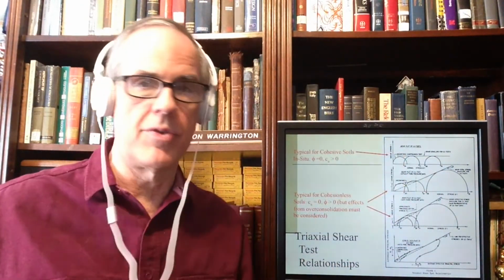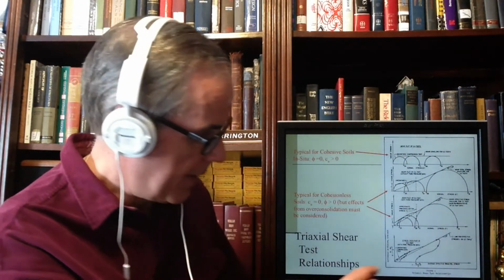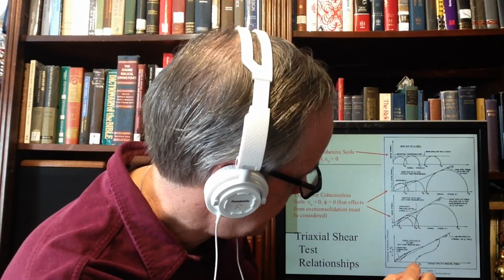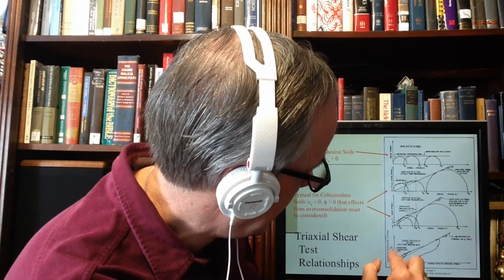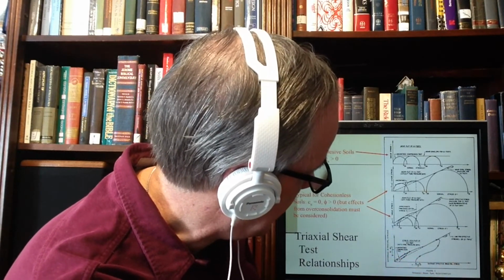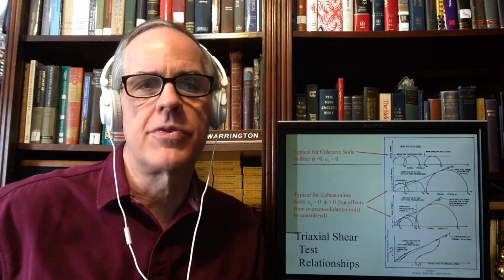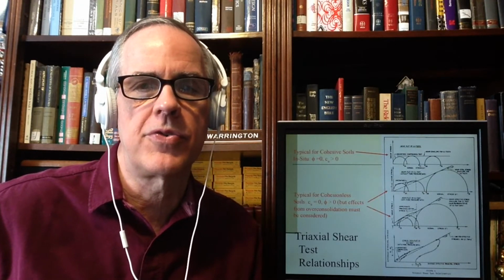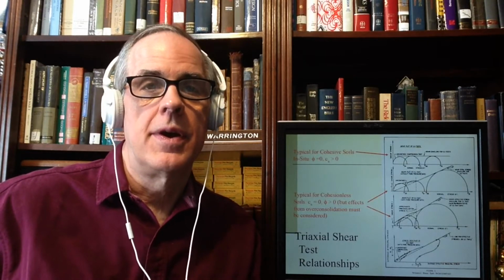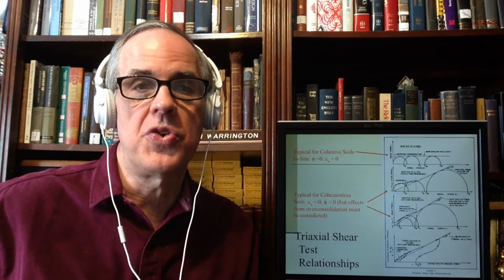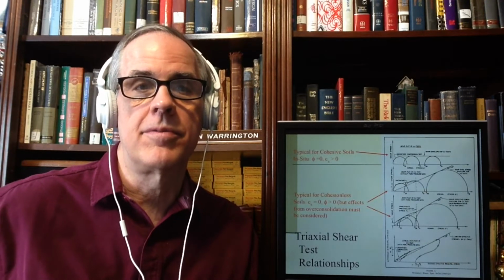This is what I was talking about with the cohesionless soils, and we actually take advantage of this when we get to the UC test. This is a stress path diagram using the PQ diagram, and this is your classic PQ diagram. Usually that's where PQ diagrams are used most often, with stress path analysis. Stress path analysis is something I'm not going to get into in this course, but it's frequently important to determine, if we have a stress history, it may be easier to predict what the soil will do if we add to the stress history.